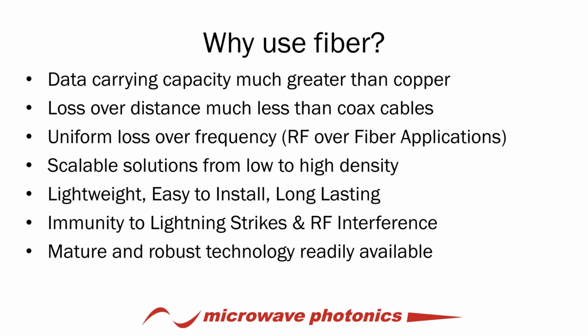So you won't see the contribution of slope from the RF photonic transport over many kilometers that you would if you were to have traditional coaxial waveguides. The other main reason to use fiber is that it does offer immunity to lightning strikes and RF interference and an added layer of security. And while there's some other bullets listed there, those really are the main reasons.